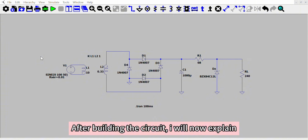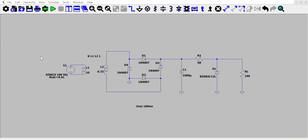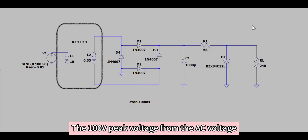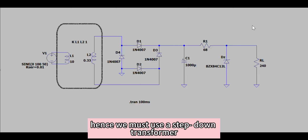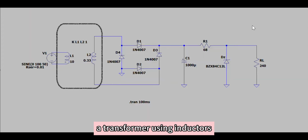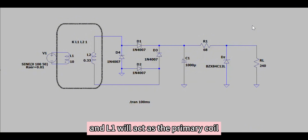After building the circuit, I will now explain the working principle of the circuit. Firstly, for the transformer part, the 100 V peak voltage from the AC voltage source is too high for our desired usage. Hence, we must use a step-down transformer to reduce the voltage. In order to model a transformer using inductors, we will use a specific formula to get the step-down ratio, and L1 will act as the primary coil, L2 will act as the secondary coil.